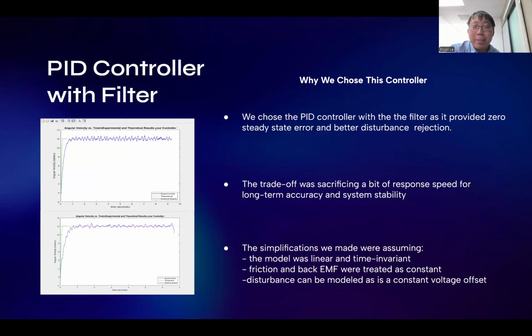The simplifications we used were that the model was linear and time invariant. Friction and back EMF were treated as constants. And disturbances were modeled as a constant voltage offset.